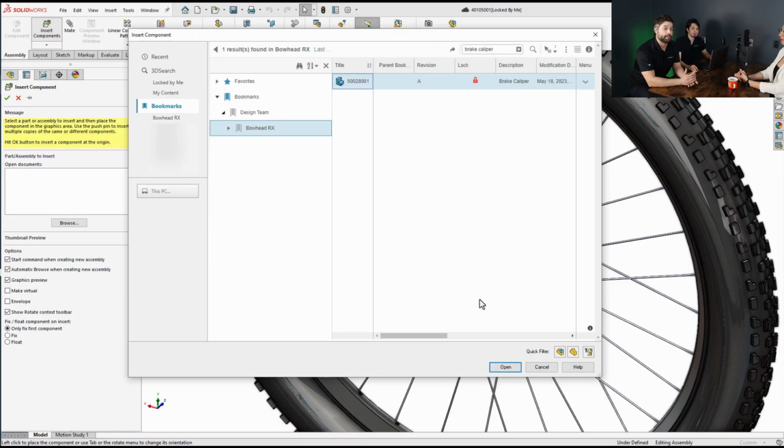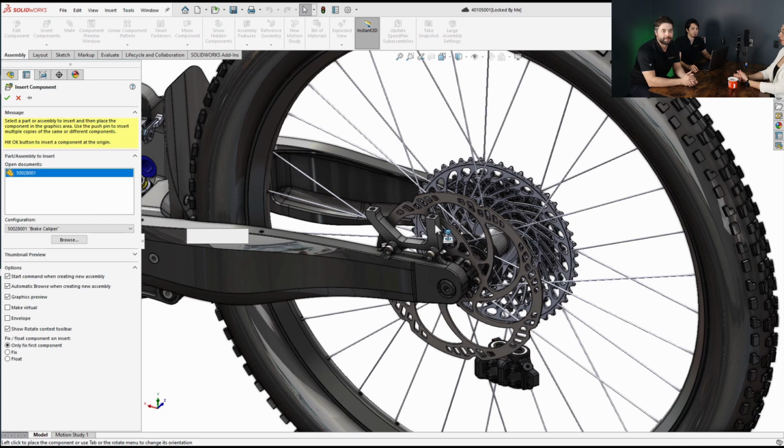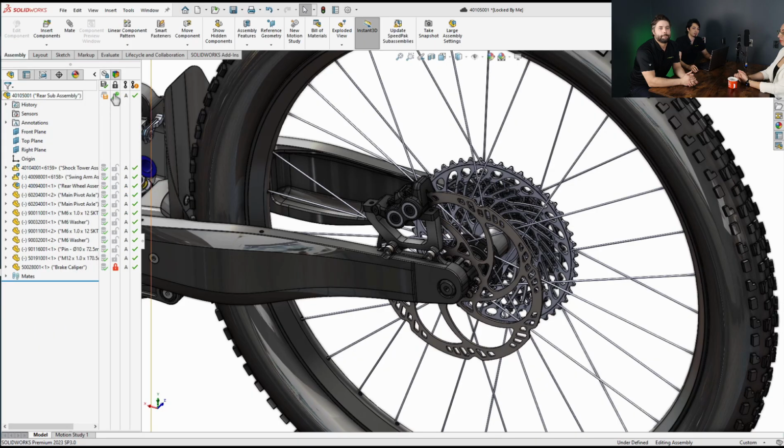If you have more designs to work with, you can save them locally with Save to this PC, or as always, Control-S. And when you're ready to put some changes on the cloud storage, use Save to 3D Experience, and it'll update what was previously stored on the cloud.